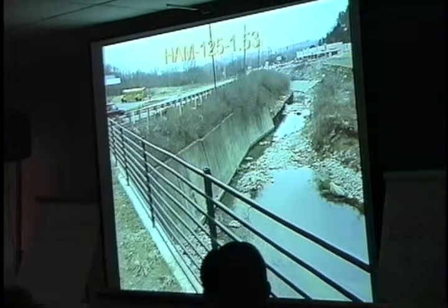And this creek here is connected to the Ohio River, and so I guess flows through here can be extremely rapid. So the scour was something that wasn't necessarily going to go away. Plus, we couldn't do anything with the stream with respect to just simply creating a toe there again for this counterfort wall. So the solution in this case was actually to introduce a 4th type of wall. We're going to put in drilled caissons, cantilever caissons socketed into rock along the roadway here.